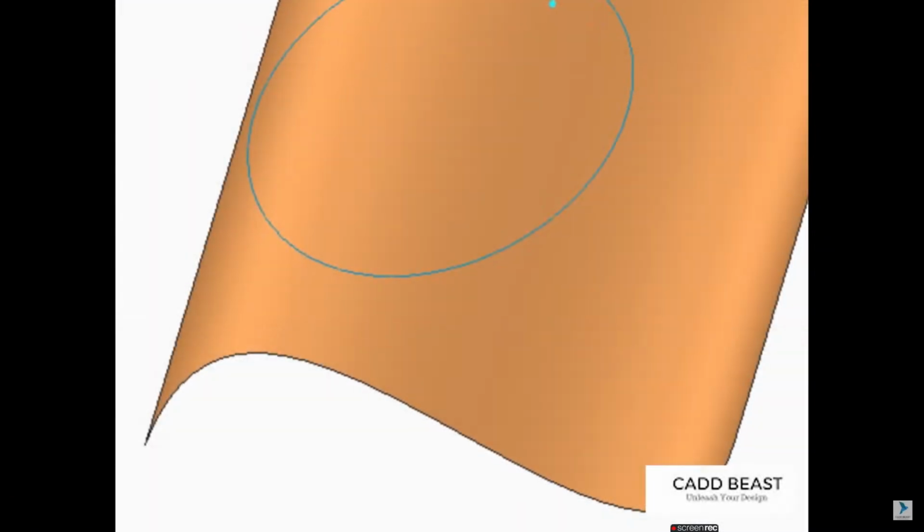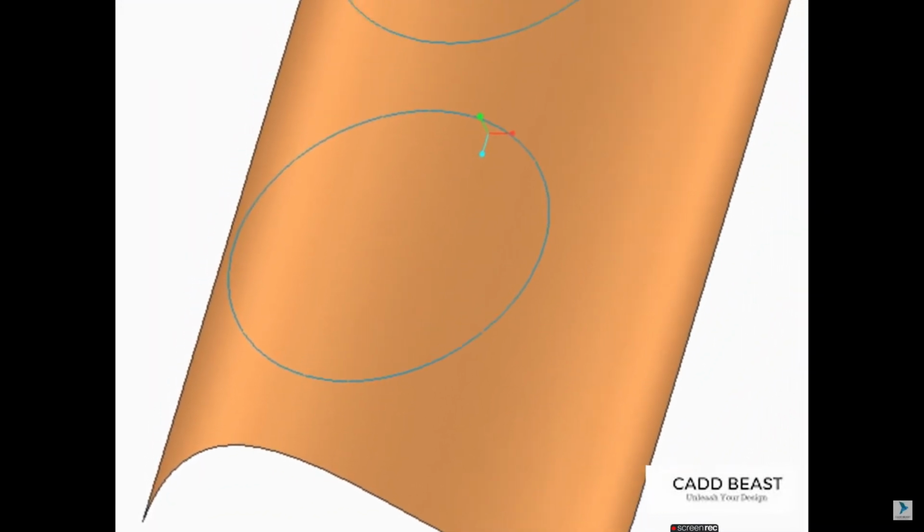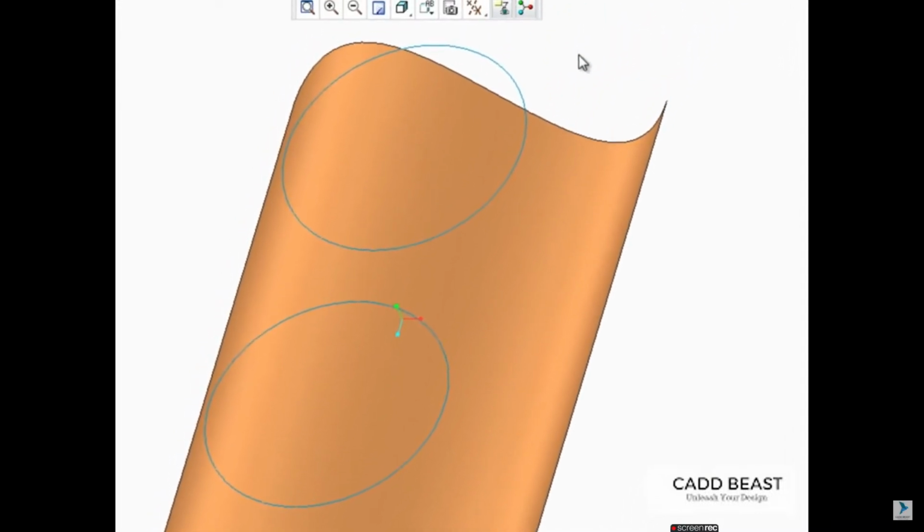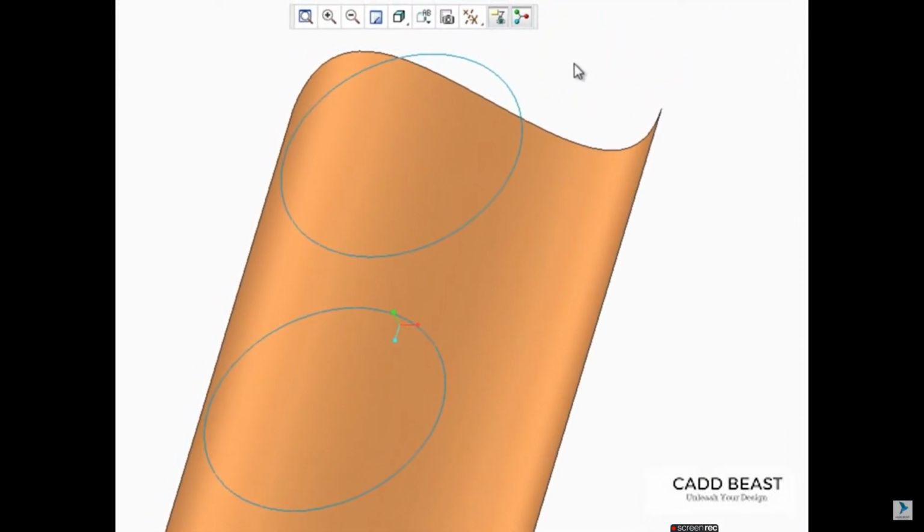You can project or wrap a selected curve onto a surface or a set of surfaces. When you're projecting a curve, depending on the shape of the surface and the angle of the directional reference plane, the length of the projected curve can increase or decrease from its original size. Let's perform some projection examples on this curve. We'll get to wraps with the other curve later.